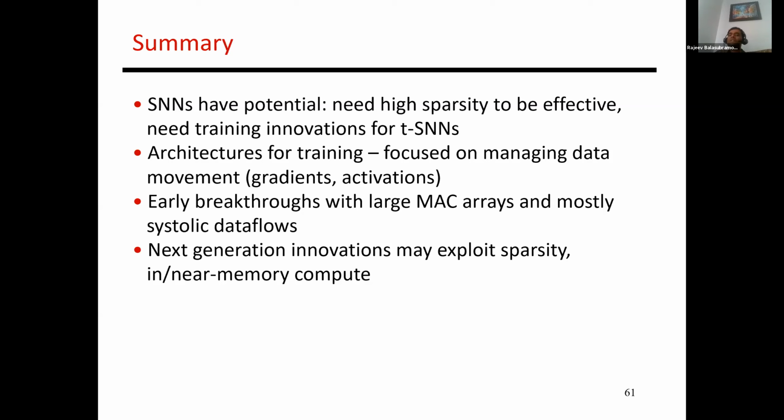So one option is to say that there are 30 possible neurons out there. So let me implement a different hardware for each one of those neurons, right? And that would be the CISC approach, where you're implementing a different instruction for every single operation that you can possibly have. Whereas I think the TrueNorth approach is more the RISC-like approach, which is saying that I'm going to implement one specific LIF, but it has various configuration parameters. And so I can set them, or I can club together multiple neurons, and that can implement these 30 different neuron types. So that's kind of what they have done.